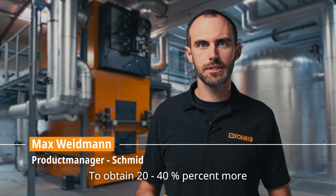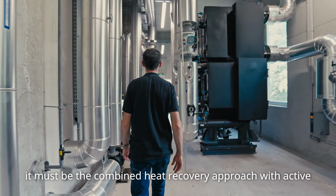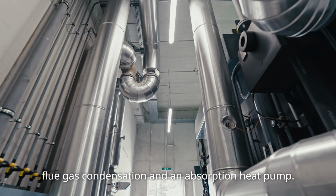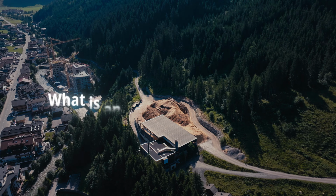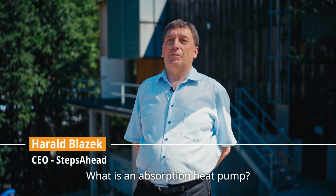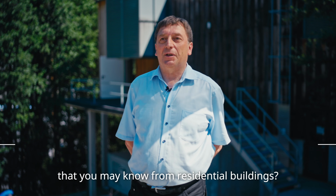To obtain 20 to 40% more heat from the same amount of fuel, it must be the combined heat recovery approach with active flue gas condensation and an absorption heat pump. What is an absorption heat pump? How does it differ from a compression heat pump that you may know from residential buildings?